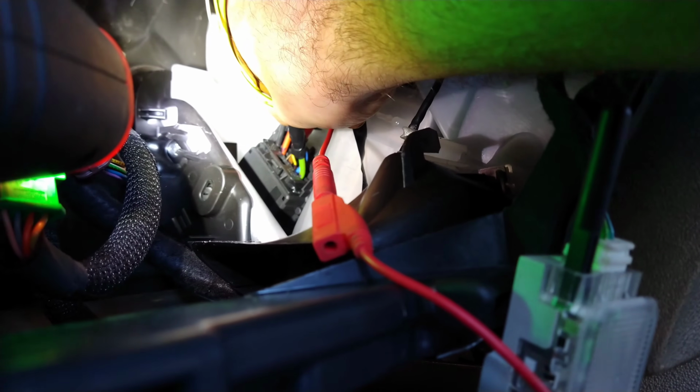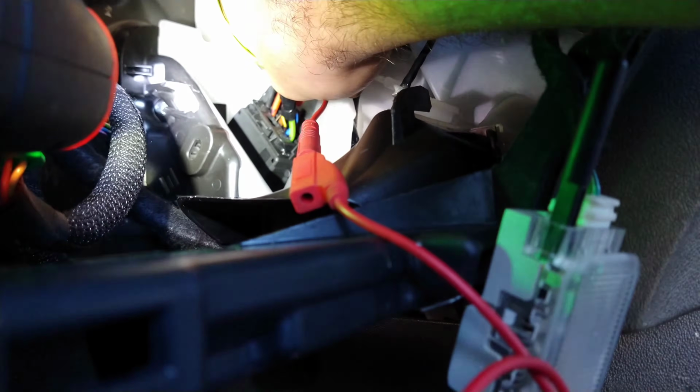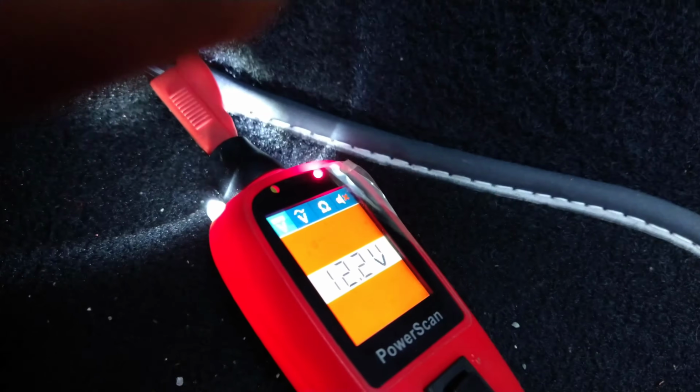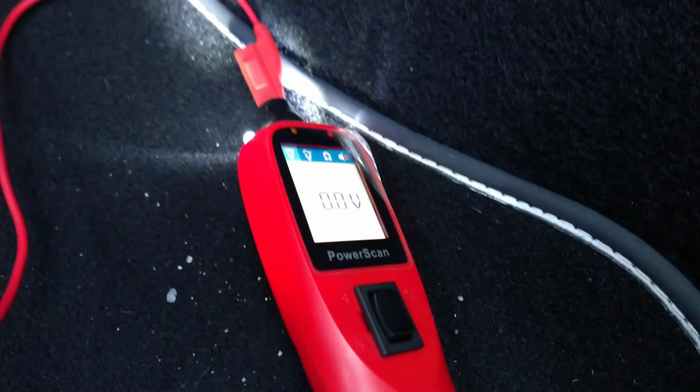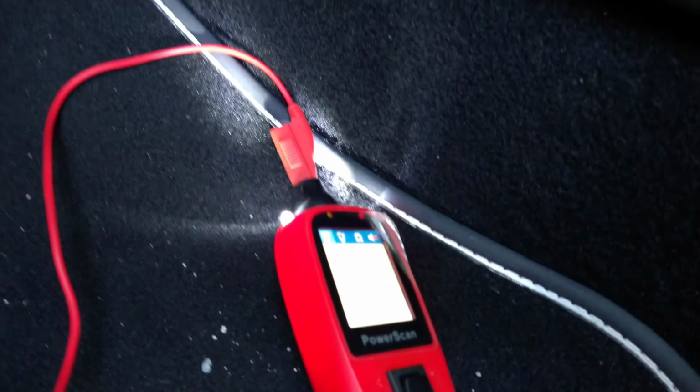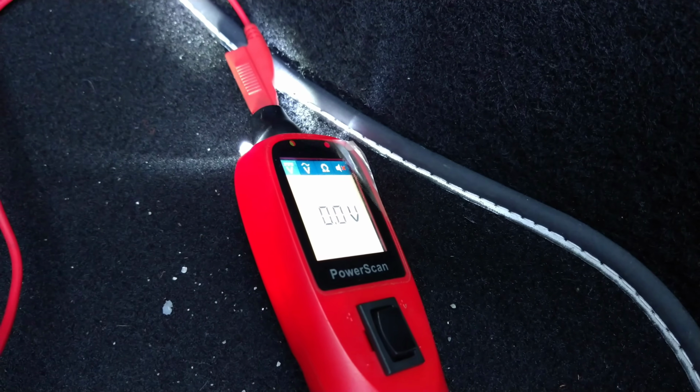The next one down is the brown. This will be the input into the module, which I'm on now, the brown one. And that's red as well, so we've got power in. I've dropped my light. Okay, the next two, small control wires. And the very bottom big one should be a ground. And it's not, that should be green, you see, if it's a ground. So we're missing a ground. So that's why it's not working, it needs the ground to work.